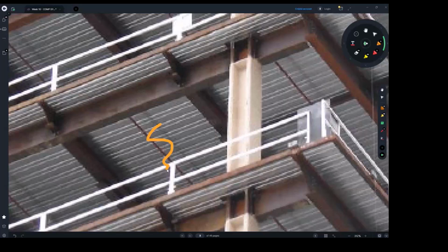And if you want to resist fire between apartments, you have to put special plasterboard materials. Now, in car parks, this is not achievable. You won't be putting a plaster under the concrete slab. So that's why sometimes in car parks, if fire rating is required, you're going to need to not use bonding. You may not see bonding below because you want concrete